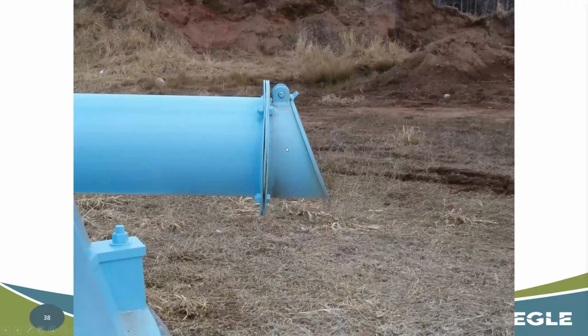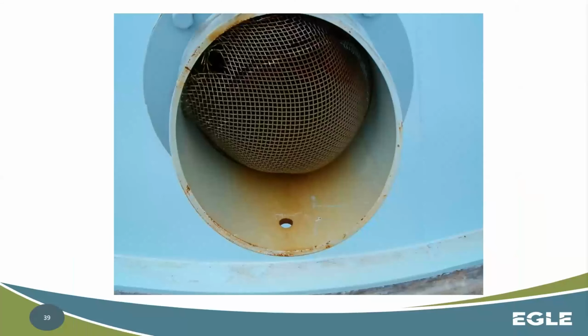But the concern here is if you have any overflow during the winter, now you don't have any gap for that to release. So maybe putting a welded bead on here is recommended, or putting a little bit of relief here, so that any trickling of water might be able to leak out. Okay, rather than sealing that flap shut. Now it's basically not worthwhile. Okay, now it's building ice back up into that tube, into that overflow route, and you can have some issues that way as well. So I'm not sure if it's the same tank, but it might be.